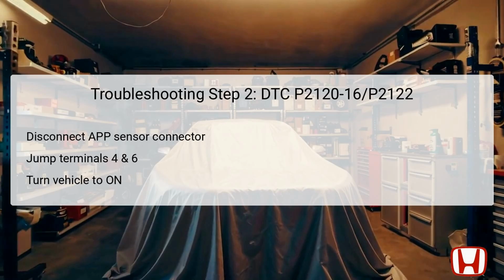This action simulates a normal operating condition for the sensor. Next, the vehicle should be turned to the ON mode again, allowing the technician to verify the APP sensor A voltage reading. A normal condition should show a voltage greater than 0.2 volts.